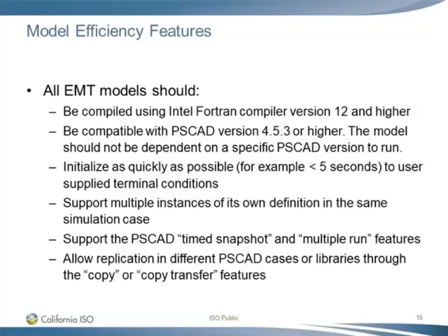All EMT models should initialize as quickly as possible, for example, less than 5 seconds, to user-supplied terminal conditions, and support multiple instances of its own definition in the same simulation case. All EMT models should also support the PSCAD time snapshot and multiple run features, and allow replication in different PSCAD cases or libraries through the copy or copy transfer features.